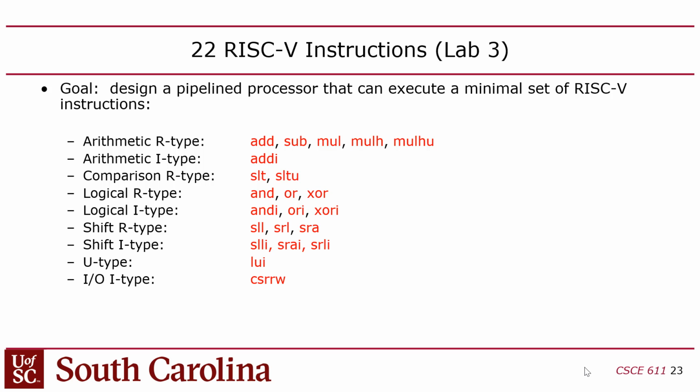The reason we have that in there is because we want you to be able to build an application that's interactive through the FPGA board. We want to use the switches, kind of like you did in Lab 2, except in Lab 2 you just created logic that you connected directly to the switches. Now we want to create a path to get the data from the switches into the CPU, into a register that you can then read from with an instruction and number crunch on.